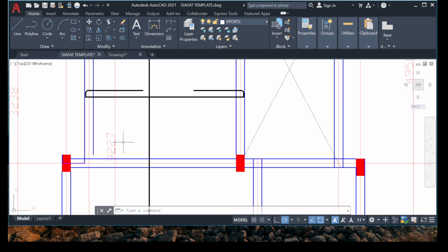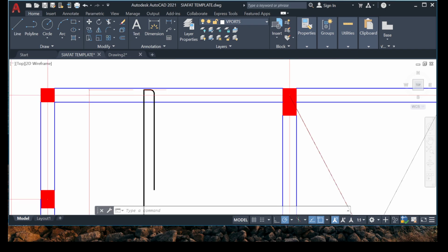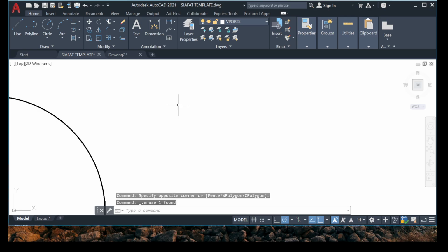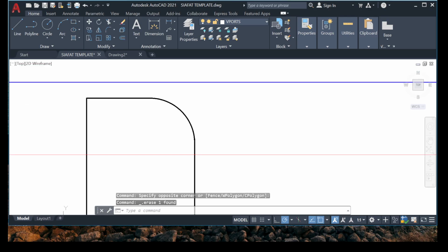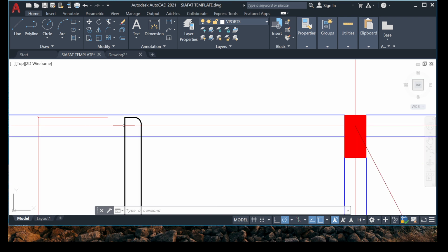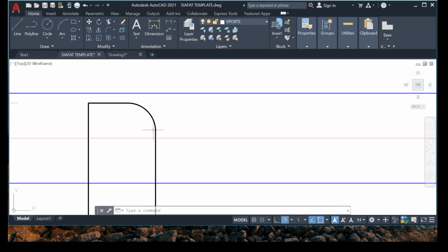Now remember that a reinforcement is 12 mm. Now okay, let me tell you how we got this. This one is gotten after you've actually removed the concrete cover. Now the slab thickness is 150 millimeter. So 150 millimeter minus concrete cover 25 on each side, that's 50. So this one is 100.